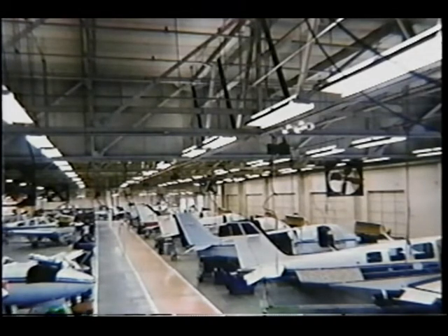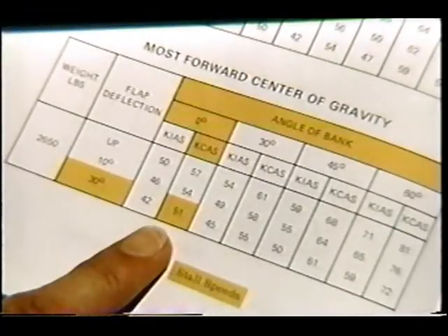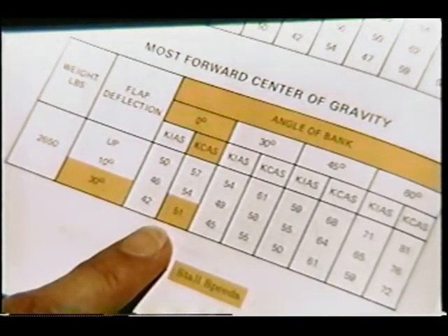Calibrated, of course, is indicated airspeed corrected for position and instrument error. Now, how is that significant? Well, just as an example, it means that if you want to calculate your approach speeds and you're flying in one of these latter-day airplanes, you've got to go to the handbook and check the stall speed tables to find out what VSO is in calibrated airspeed.